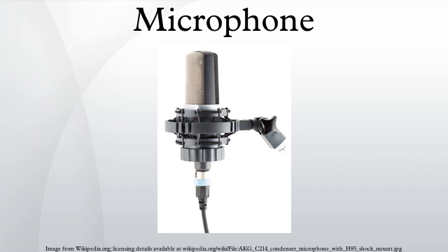Some new modern ribbon microphone designs incorporate a preamplifier and, therefore, do require phantom power. Circuits of modern passive ribbon microphones, that is, those without the aforementioned preamplifier, are specifically designed to resist damage to the ribbon and transformer by phantom power. Also, there are new ribbon materials available that are immune to wind blasts and phantom power.